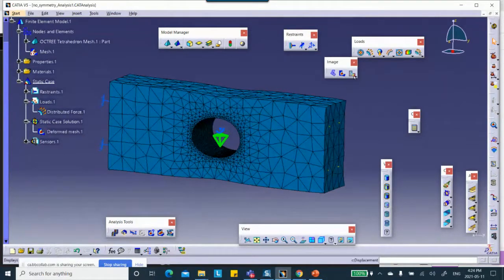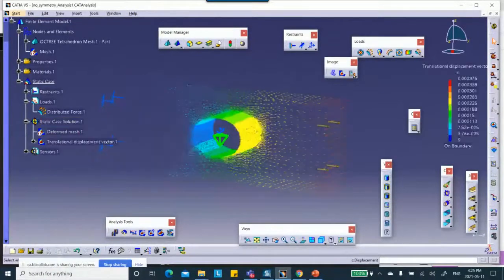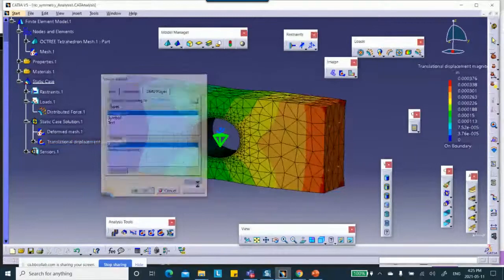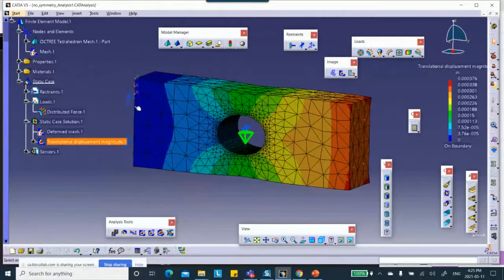All right, now let's look at the displacement. This is the deformation. It's not numbers, okay? Displacement is right here. Let's change it to average ISO. There we are. This end is clamped. It is fixed. This end is moving. Biggest displacement is on the right. And you can see that that's reasonable. These are small stresses. Well, but this is not gum either. This is a piece of steel, aluminum 2 inches by 4 inches by 10 inches. So it's not going to stretch like crazy.